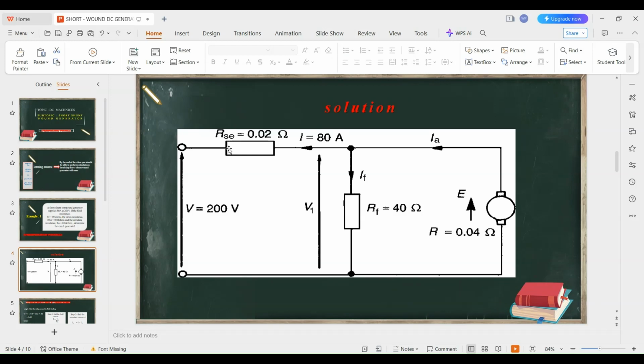So step one, we've said, is to look for the voltage drop across the series resistance. We've been given the current flowing through that series resistor as 50 amperes and the resistance as 0.03 ohms. Therefore, when you key these values into your calculator, we shall get 1.5 volts. Let's look at step 2. Step 2 says we look for the terminal voltage. How do we calculate the terminal voltage?